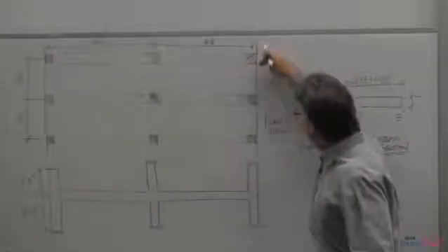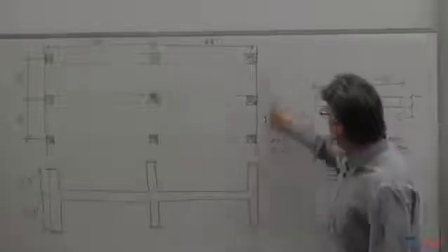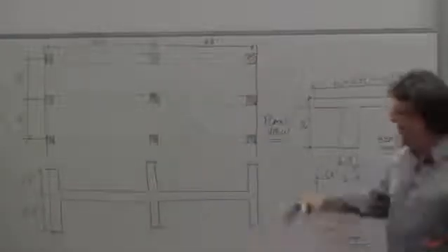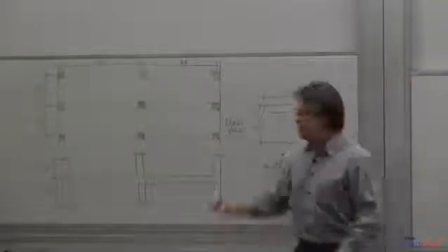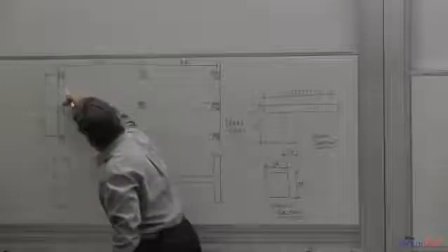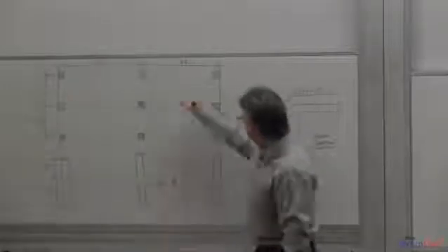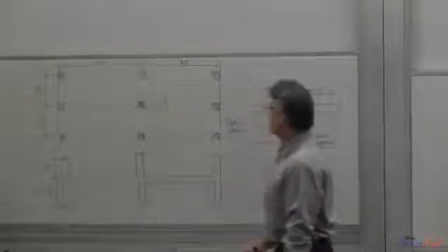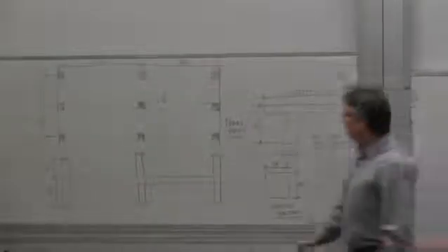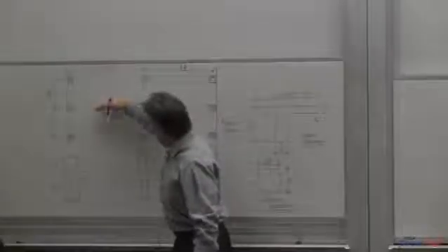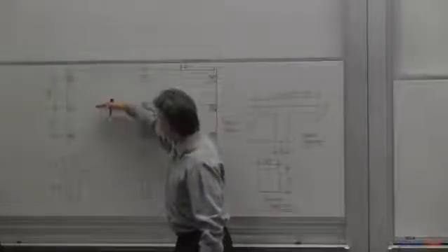But both of us are going to have a 2-span beam. This is a plan view. So I'm looking down at a plan. These beams just keep repeating. I've drawn a section of the floor system, and these will keep repeating until the geometry of the building changes. Maybe it will grow out here later towards the north or the south, and you frame it differently. But this is a section of it. Each beam is spaced at 18 feet on center. So we'll design this beam. This beam has a tributary area of 18 feet. 9 feet on this side that load is going to be assumed to come here. 9 feet on this side is going to be assumed to be supported on that beam. Tributary area.